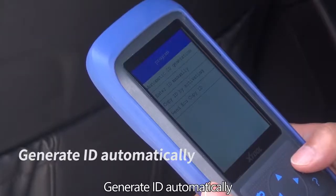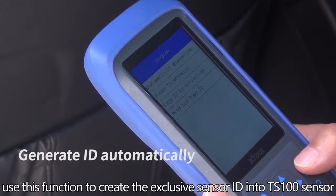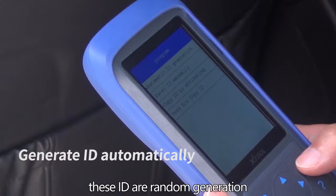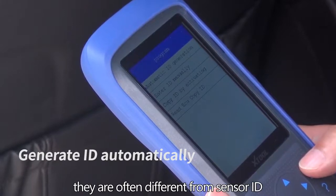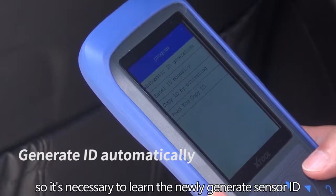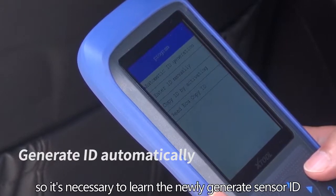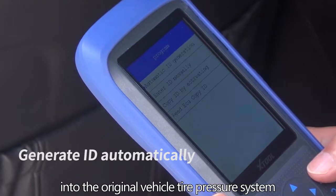Generate ID automatically. Use this function to create the exclusive sensor ID into TS100 sensor. These IDs are random generation. They are often different from sensor ID which is stored by original vehicle tire pressure system. So it is necessary to learn the newly generated sensor ID into the original vehicle tire pressure system.